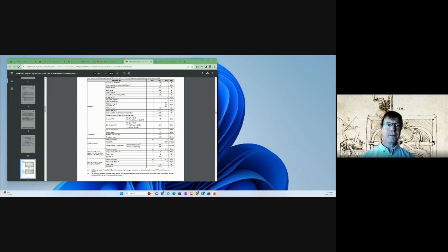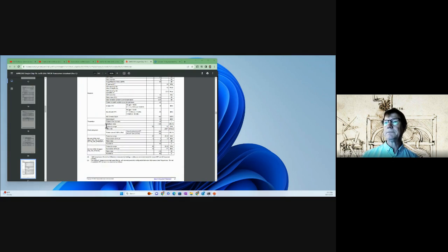But we're not breaking Shannon-Nyquist theorem here. We're basically taking 2 samples, and we need 2 ADCs, and we need 2 signal paths after down conversion. That one is isolated on the real part of the signal, and the other one's isolated on the imaginary part of the signal. So we have 2 samples for every time that our sample clock ticks, right? So that's why you're seeing 2 different values here.